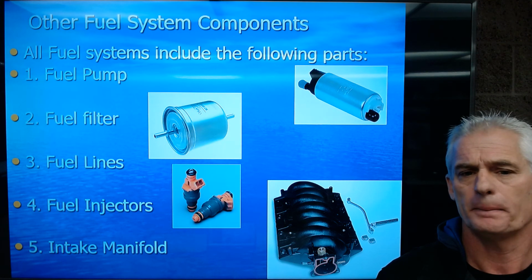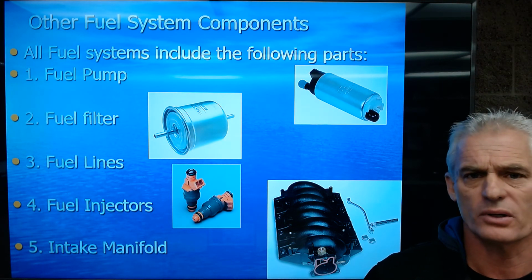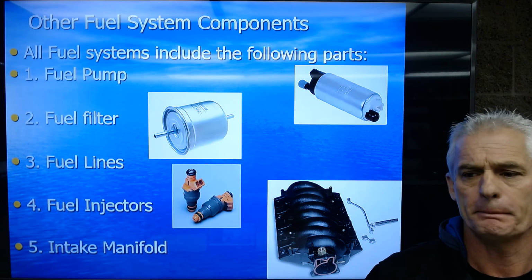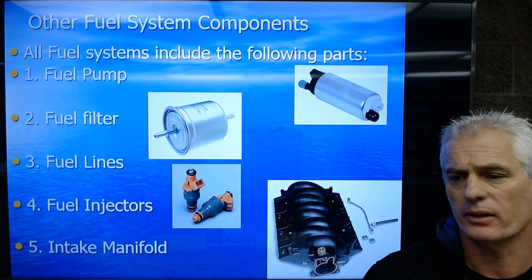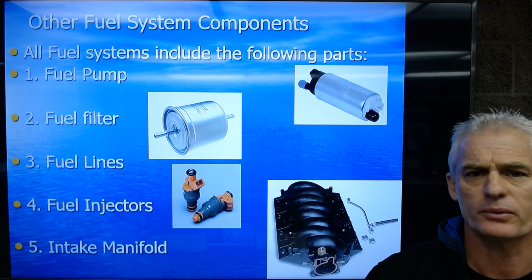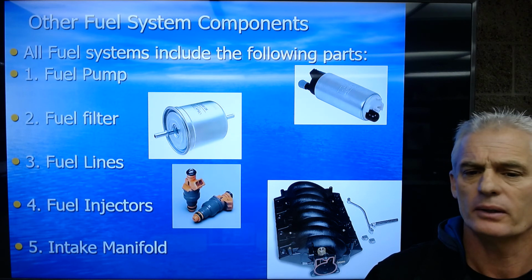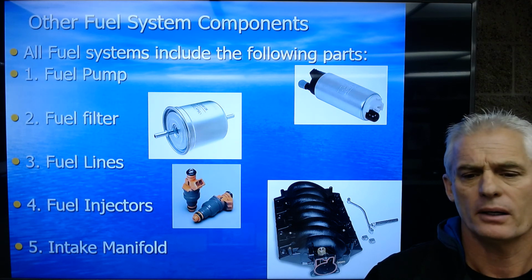Okay. Just as a comment, fuel systems today on modern vehicles are very bulletproof. There's very few things that go wrong, and very little servicing needed. We can run a fuel system cleaner every other year, at 30,000 miles perhaps, through the fuel system to keep the injector tips cleaned out. Changing the fuel filter, if it's easily done, we can do that.